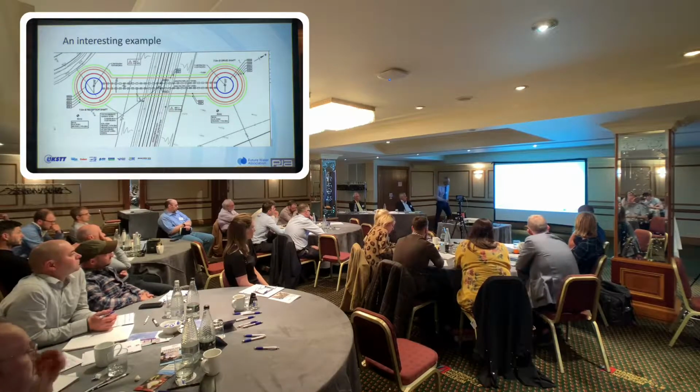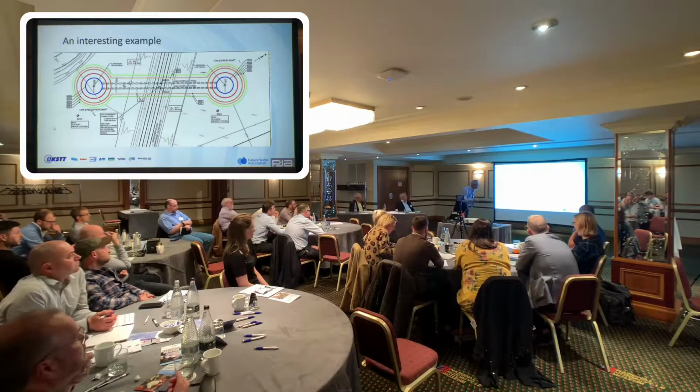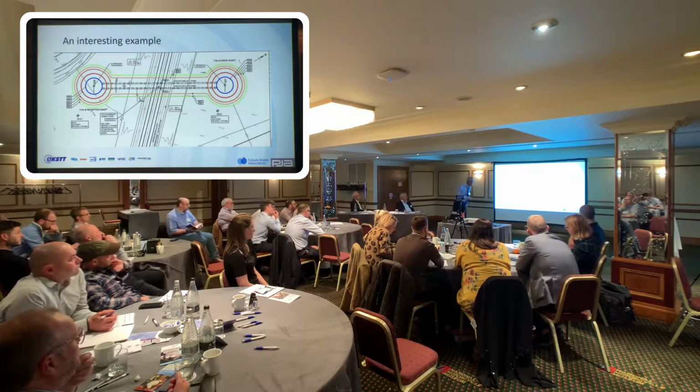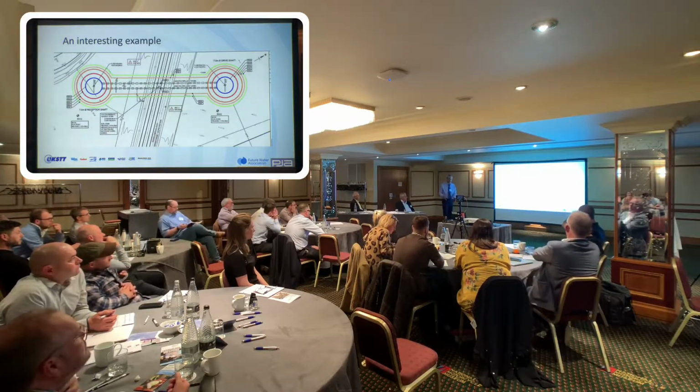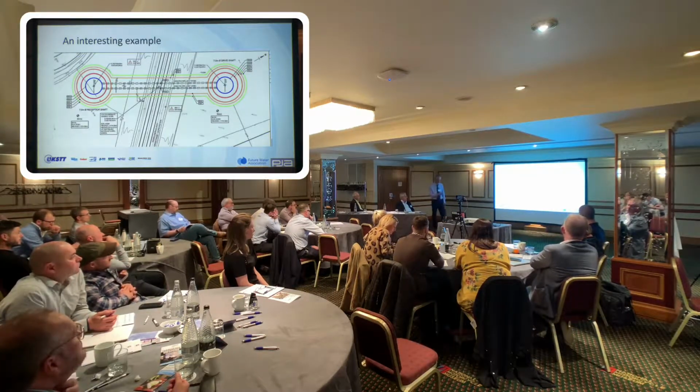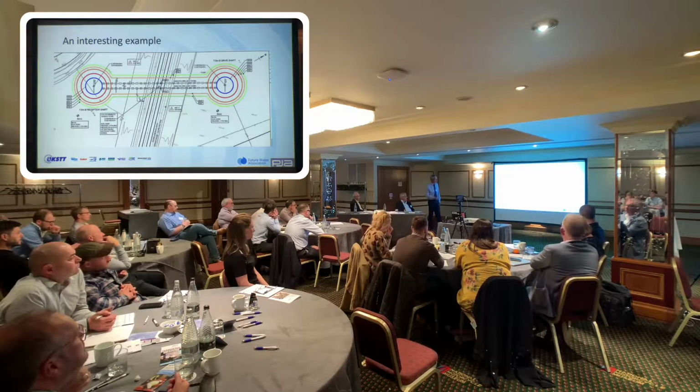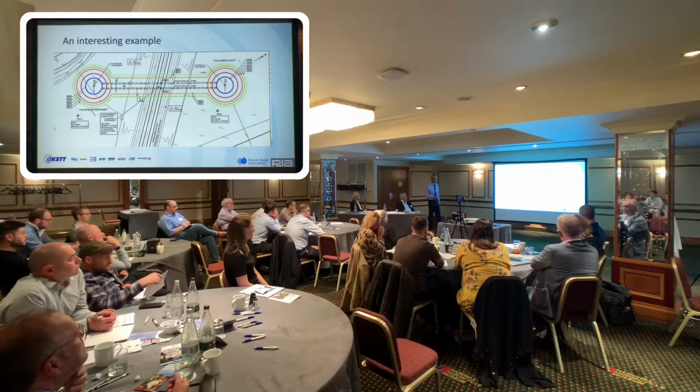I can't actually read those. Yeah, the green line's 1 mil, and the blue line is 18 millimetres, but that is a combined effect from the shaft sinking operation and the tunneling operation, which again needs to be considered because it's a cumulative effect.